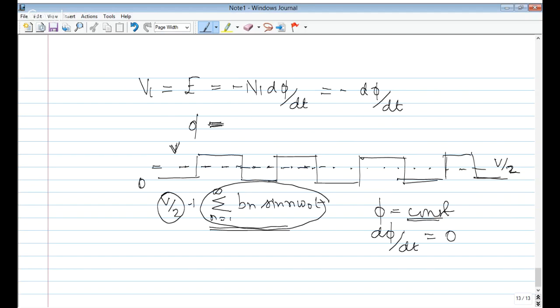So what I feel is the answer should actually be D. There will be impulses across the secondary winding based on the derivative of this. Because here the pulse goes from 0 to positive, so positive impulse, negative impulse, positive impulse, negative impulse. I think the waveform should be like this because DC cannot get induced across the secondary. Only AC can get transformed, and when we take AC, we get an impulse-like waveform, that is, an alternating waveform. We cannot have a DC value. That is, the waveform should be alternating in polarity.